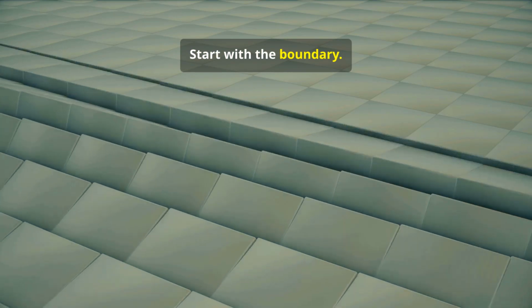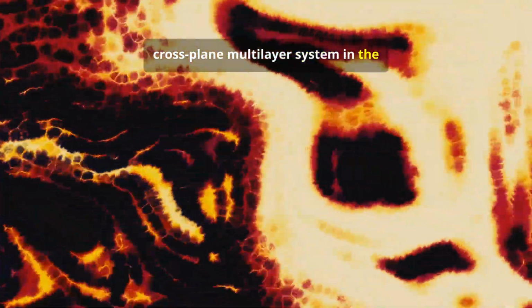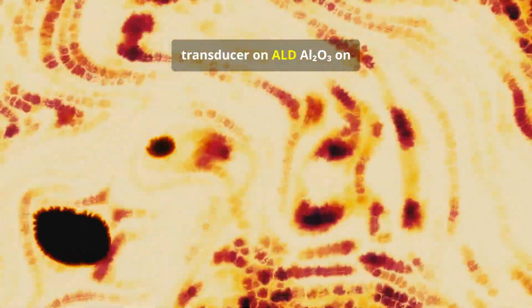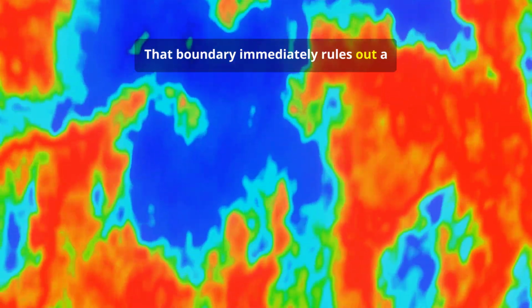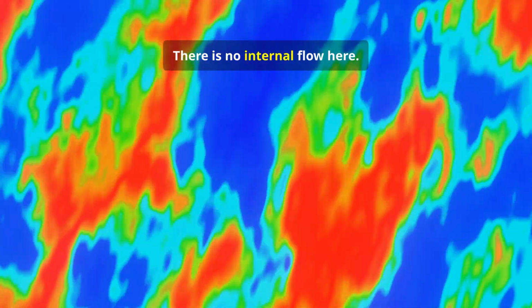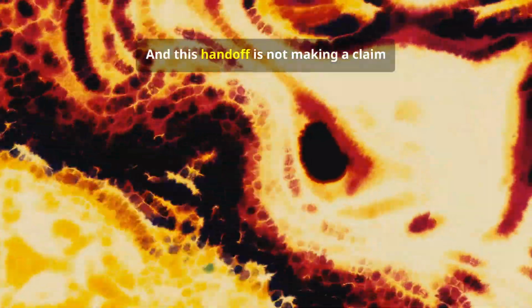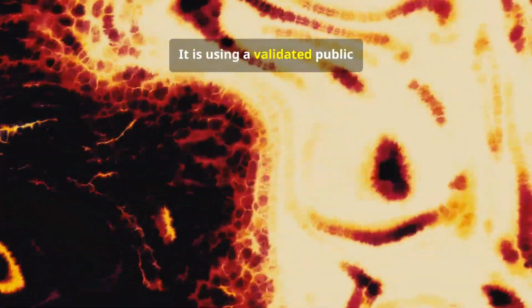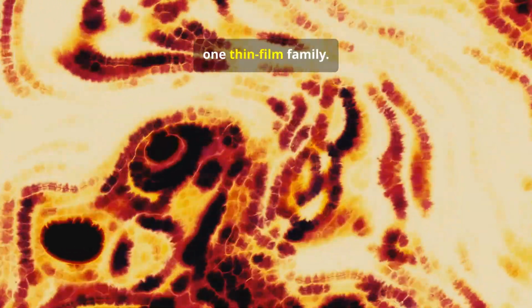Start with the boundary. The packet closes on a planar, cross-plane multilayer system in the thermoreflectance family, an aluminum transducer on ALD Al2O3 on native-oxide-present silicon. That boundary immediately rules out a lot of stories. There is no internal flow here, there is no intended phase change here. And this handoff is not making a claim about a user local specimen. It is using a validated public benchmark packet for comparison inside one thin film family.